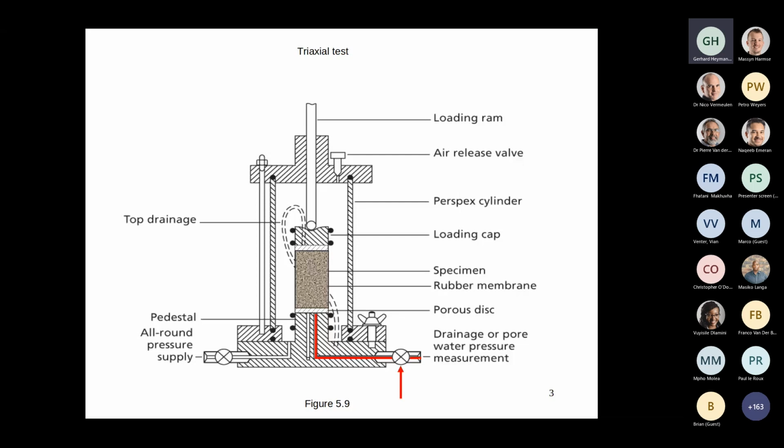Okay, so let me explain this in a slightly different way. Why only a clay and why only from below the water table? The reason is this. You need to get the specimen out of the ground to the laboratory into the cell without volume change, implying without a change in effective stress. That implies if you remove the sample from the ground, you have to remove the total stress but retain the effective stress. How is that possible? That's only possible if you develop suctions in the pore water that retain your effective stresses.